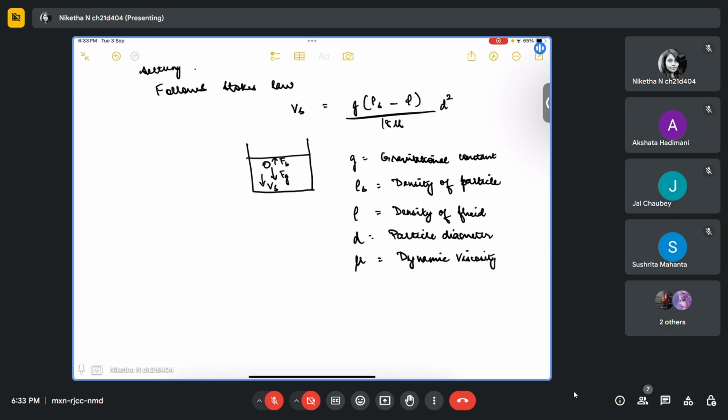Sometimes when we make the water flow inside the tank, it will have its own flow velocity which is acting horizontally. So the particle will also tend to move in a horizontal direction outwards. This is called the overflow velocity, and it will tend to move upwards and sidewards, that is away from the direction of gravity.